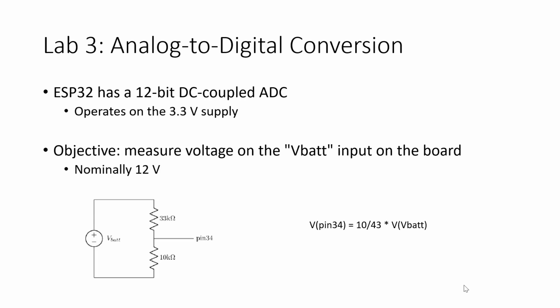Now you might ask, isn't the ESP32 powered by USB? And isn't USB 5 volts? Yeah. I don't know why this is powered on 3.3 volts. There's a voltage regulator on the board that regulates the 5 down. So the whole chip is just 3.3. Okay, so it's 3.3.